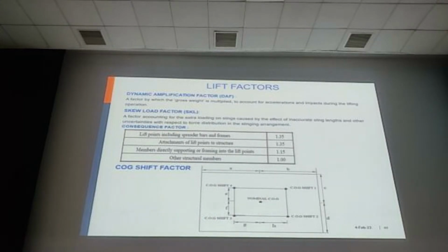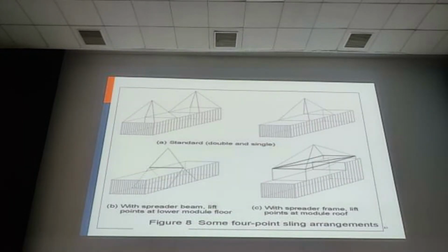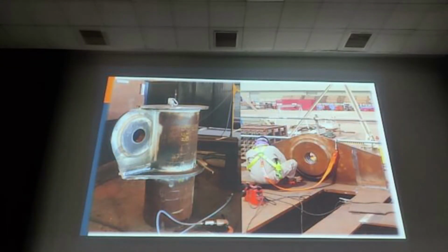All these scenarios, the possibility of COG variation and weight variation, we need to consider during the lift analysis. We can go for a better frame arrangement or better bar, or even use a dual frame. All this we have to study before configuring our system. And it's a typical headache. It's not small, it's a very big size, because our lift weight is 3,000, 4,000 tons and more.